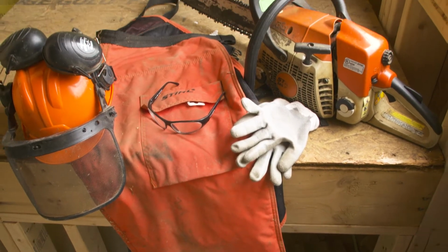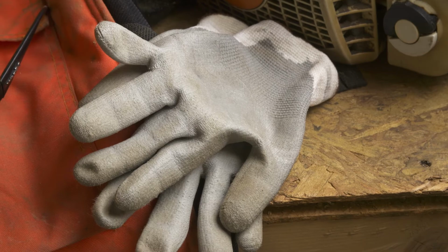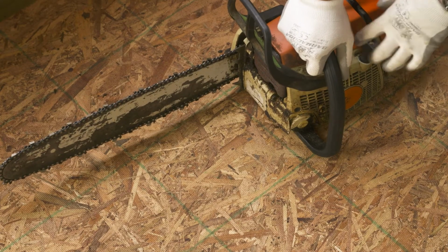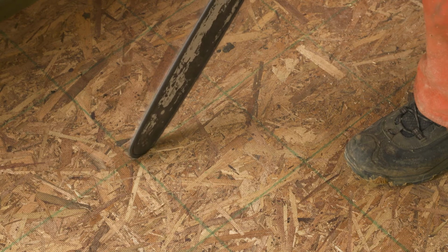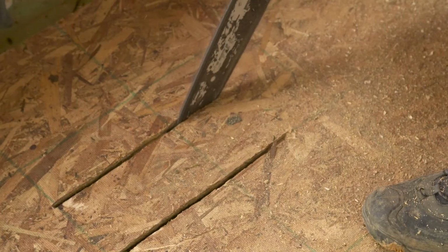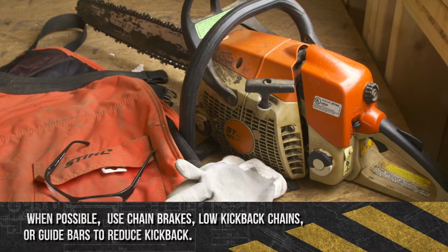Always wear PPE when operating a chainsaw, including safety glasses and face shield, hearing protection, chaps, gloves, work boots, and a hard hat. When operating a chainsaw, hold it securely with two hands and maintain stable footing. Do not cut anything other than wood, and avoid contact with nails, spikes, or other objects in the saw's path. Be prepared for kickback, and avoid cutting with the saw tip when possible. Also, use saws that reduce kickback danger, such as chain brakes, low kickback chains, or guide bars.